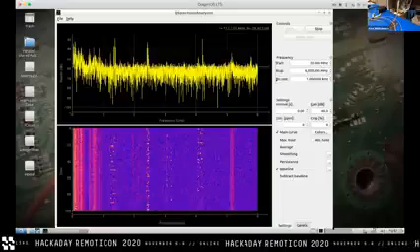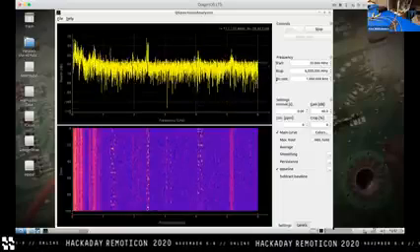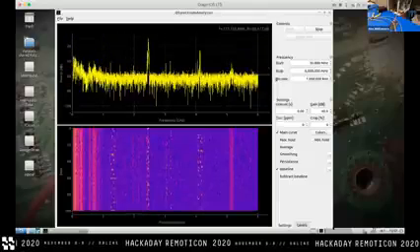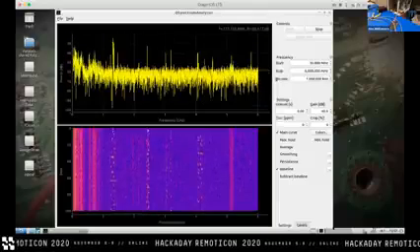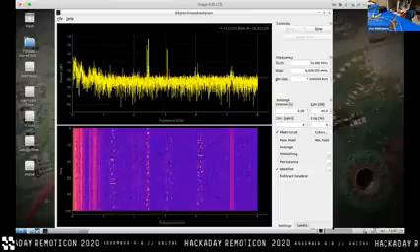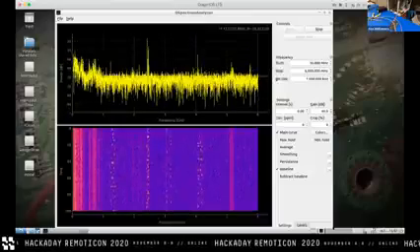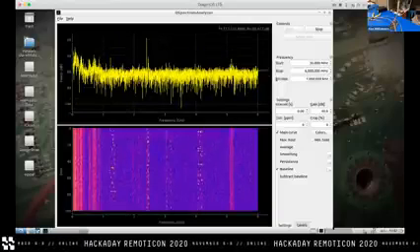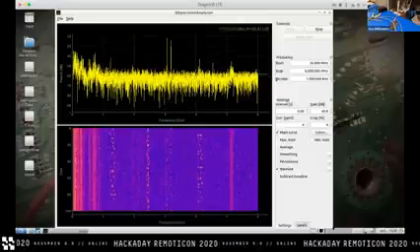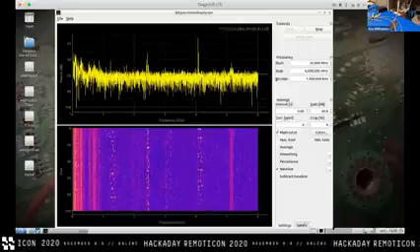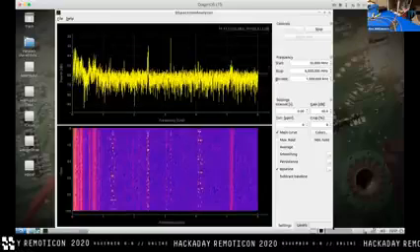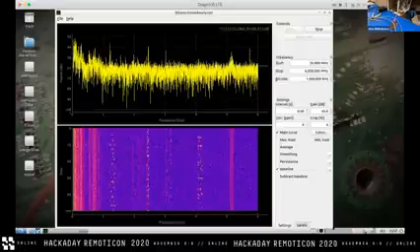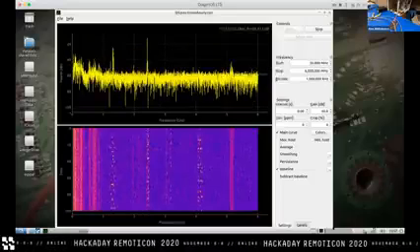So for background, for anyone else who might not be familiar, we've been covering radiated emissions primarily. Another seriously important aspect of emissions testing is conducted emissions, especially for stuff that plugs into a wall. So the question is, what kind of noise are we blasting out over the power supply, back into the rest of the household or an office or whatever? The question is basically, have you tried building your own cheap hardware for doing those sorts of measurements, which require, among other things, a line impedance stabilization network and some other hardware?